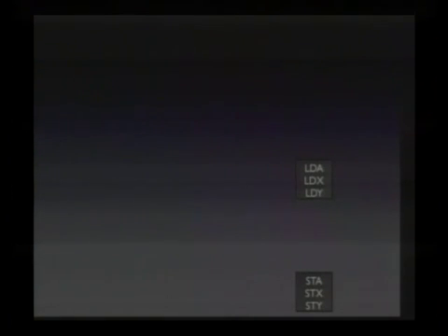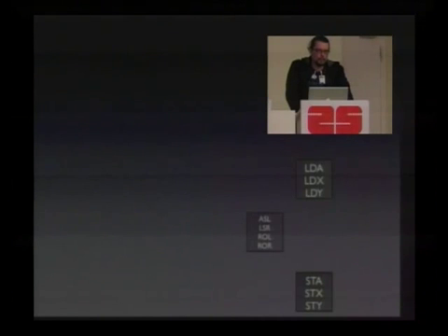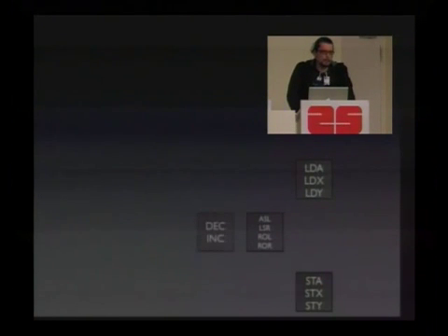This is an overview of the opcodes that it supports. Out of a possible 256 opcodes, about 150 are available. Let me give you an impression of the instruction set. There are load instructions and store instructions for those registers. You can rotate and shift only the accumulator. You can increment and decrement memory and the X and Y registers.